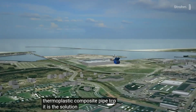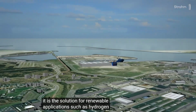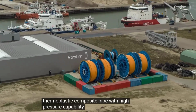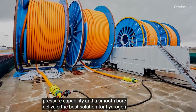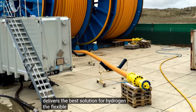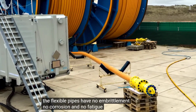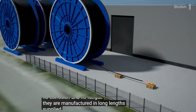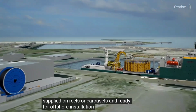It is the solution for renewable applications such as hydrogen. Thermoplastic composite pipe with high pressure capability and a smooth bore delivers the best solution for hydrogen. The flexible pipes have no embrittlement, no corrosion, and no fatigue. They are manufactured in long lengths, supplied on reels or carousels, and ready for offshore installation.